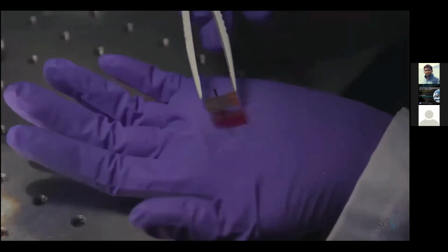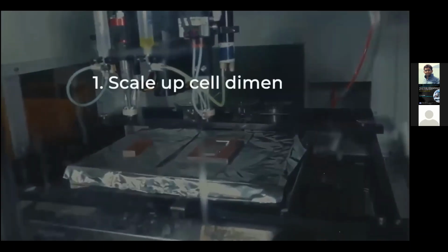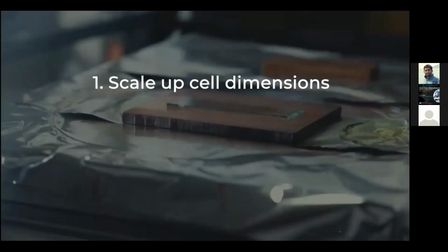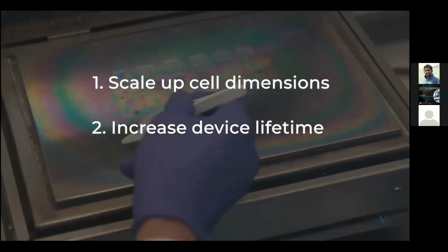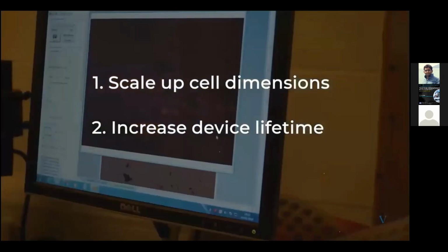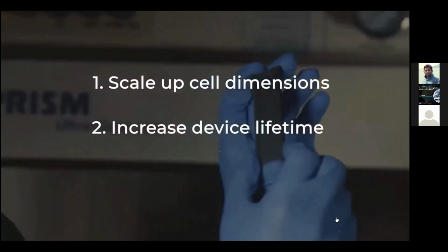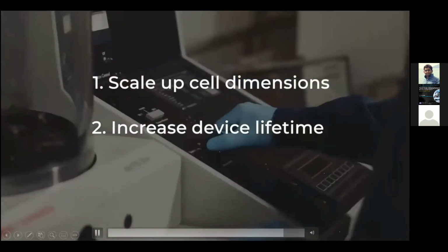The first main challenge here is to be able to scale up these cells to be large enough for solar panels, which poses both a very significant engineering and scientific task. The second main challenge is to be able to have these solar cells last for a long time. Silicon solar cells already last reliably on rooftops for around 30 years. Developing perovskites that can avoid being broken down by moisture, oxygen, and UV light is another significant task needed before perovskites will challenge silicon and ultimately fossil fuels.